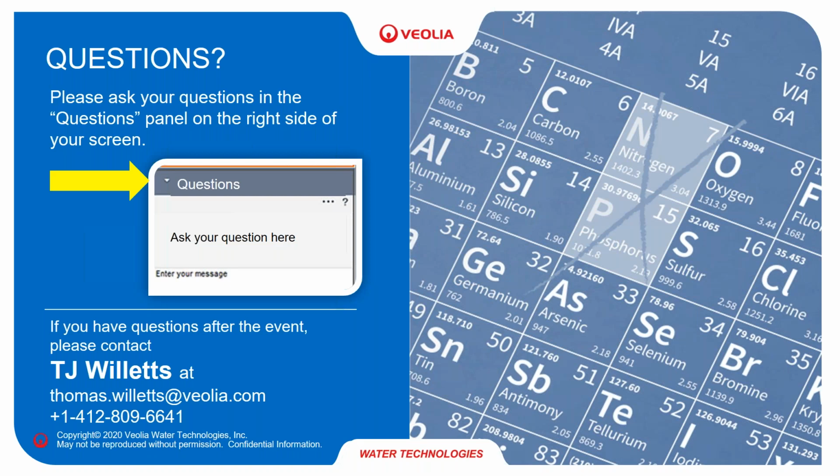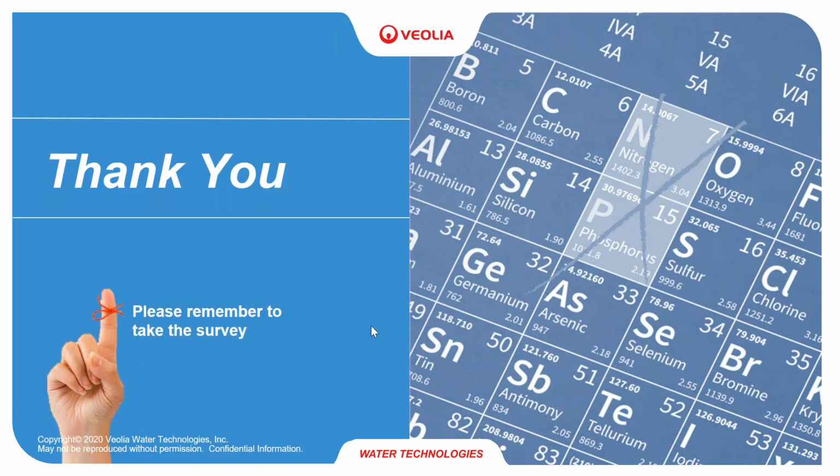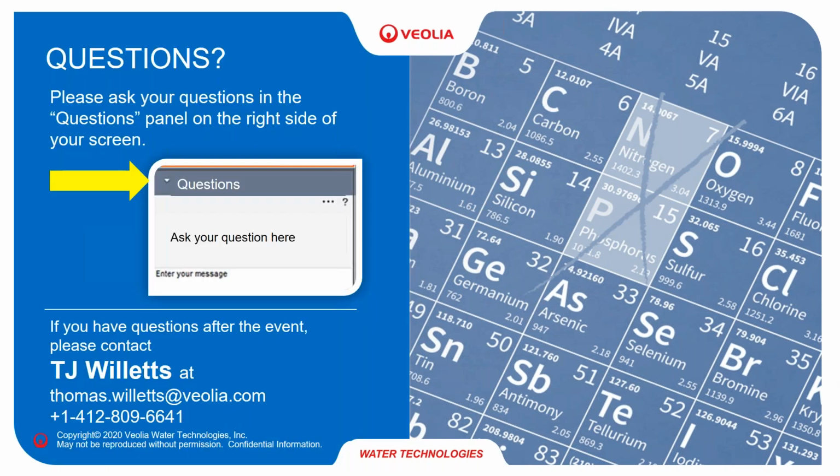Okay, it looks like we got through all of the questions that we had asked there. Oh, just one more came in. How do you identify when to use BioP over some of the other biological technologies? So BioP, once again, all I'm trying to do with BioP the majority of the time is shave off the high phosphorus. For example, if you have 5 milligrams per liter and you need to meet a discharge of 1, I probably wouldn't even consider it.